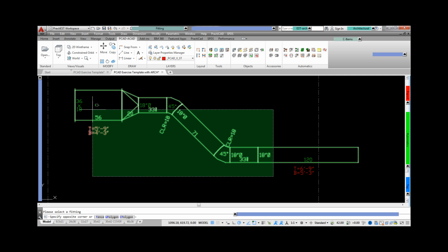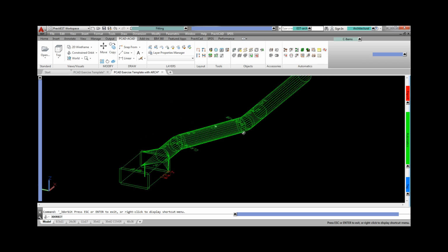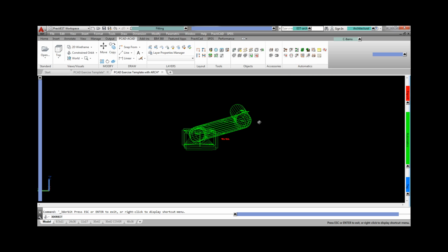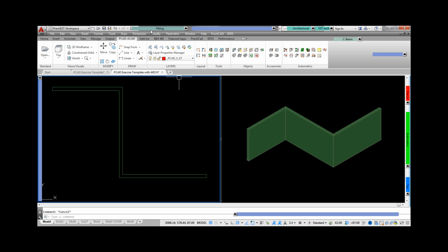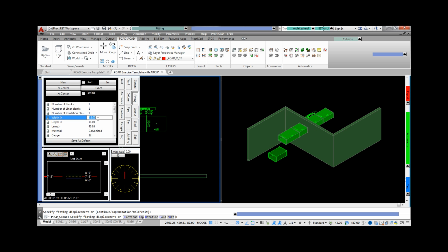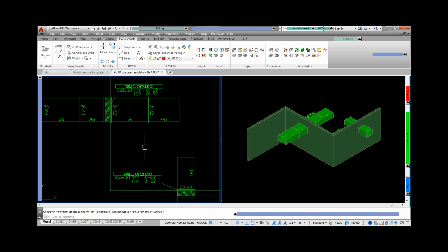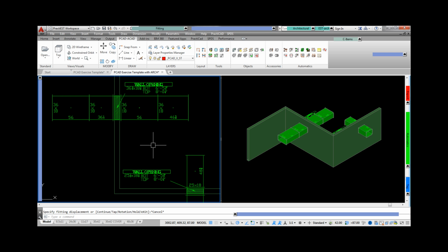Use auto routing in conjunction with PractiEst and you can see which of these scenarios is the most cost effective for your shop. But the routing options don't stop there. We can create damper routes to automate the placement of a damper inside a fire rated wall. Just grab a piece of duct, route through the wall. You can have the damper you want selected, positioned, the wall opening created, and the proper tagging to show your heights and opening size. This can greatly aid you in producing a fast wall opening drawing.